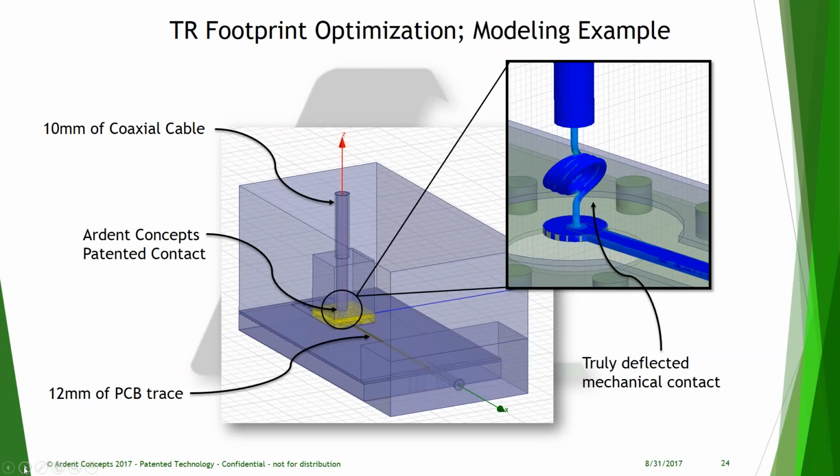The other thing that we like to do here, or something that you guys may actually be questioning, is the use of the TR device itself. Now, some customers have approached us and they've said, hey, I want to simulate your launch structure myself and I don't have your TR model. What can I do? Some of them might try to use an S2P file, and that's just not going to work. You see, the thing with an S2P file, one of the first questions that comes to mind to me is, how is that S2P file obtained?